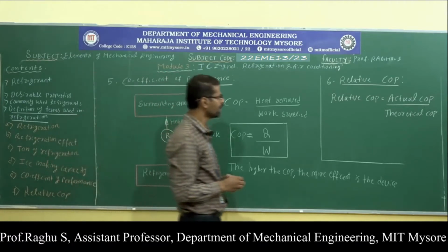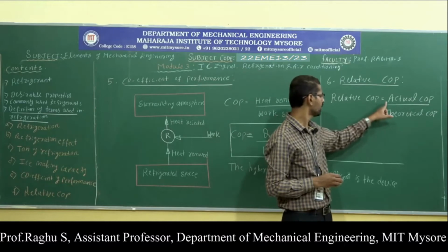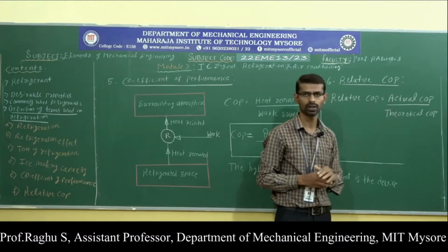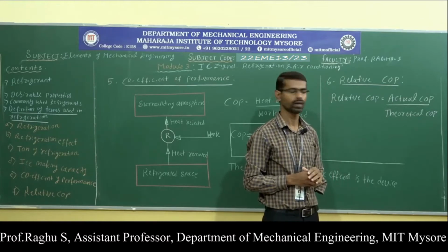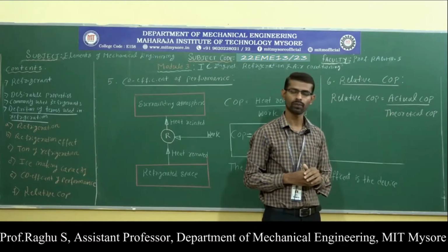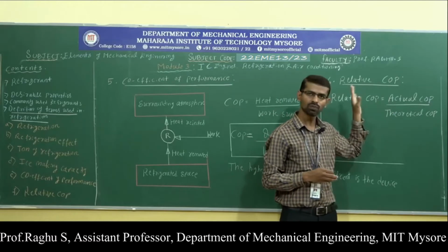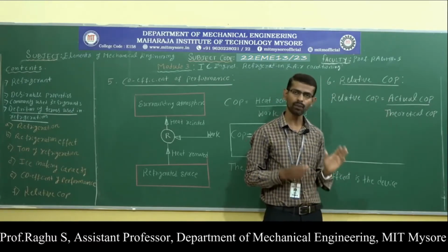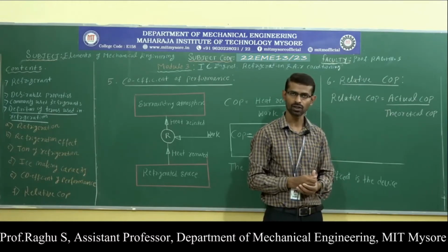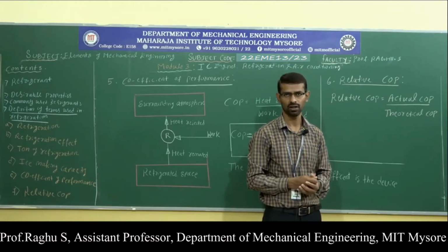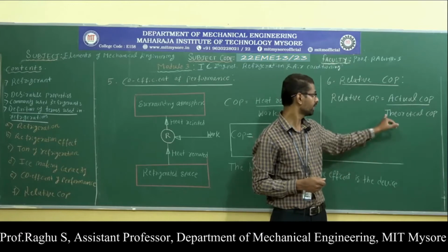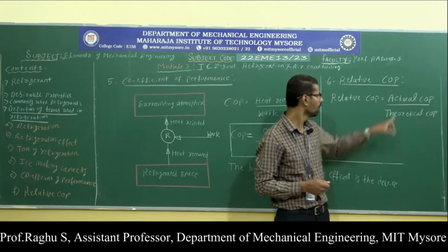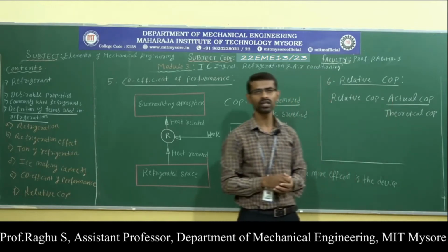The last definition, relative COP. Relative COP is defined as the ratio of actual COP to theoretical COP. Theoretical COP is obtained by applying laws of thermodynamics to the refrigeration cycle, whereas actual COP is obtained during test.